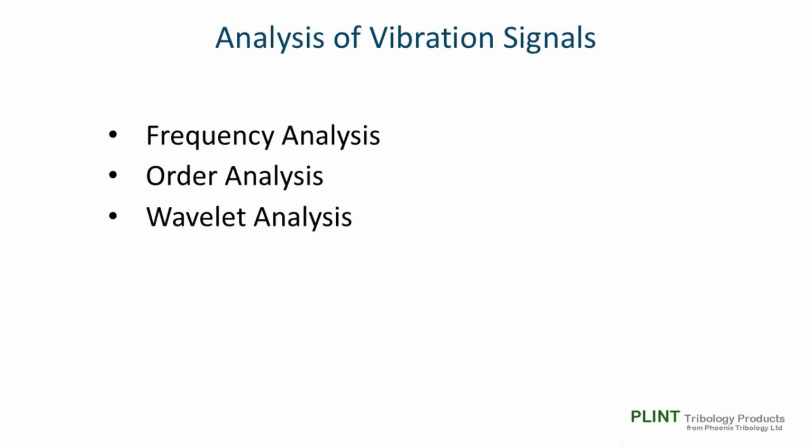Order analysis is used to analyze systems where the excitation frequency varies, for example, changes in running speed of a motor. So it is geared specifically towards the analysis of rotating machinery and how vibration levels and frequencies change as the rotational speed of the machine changes.